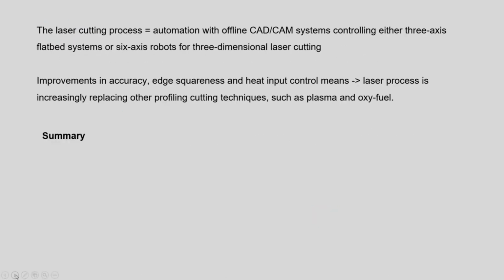When we want to implement or employ the laser cutting process, we need to have a CAD/CAM system as well. As we have seen, to generate the G and M code CNC part program, first of all we have to model the geometry. So, we first make the geometry using CAD software and then generate the CNC part program using CAM software.